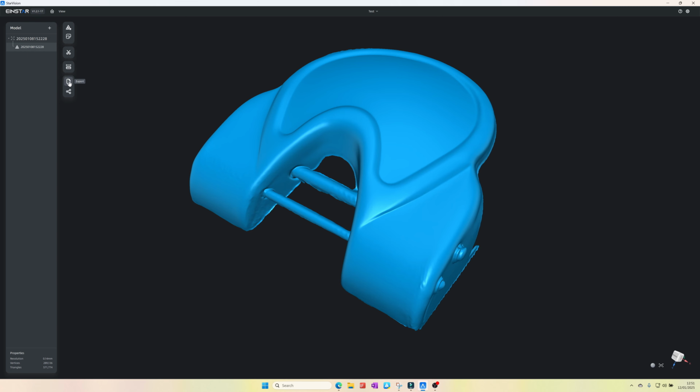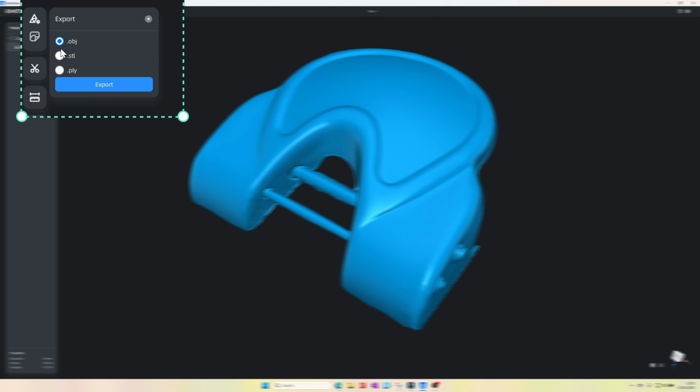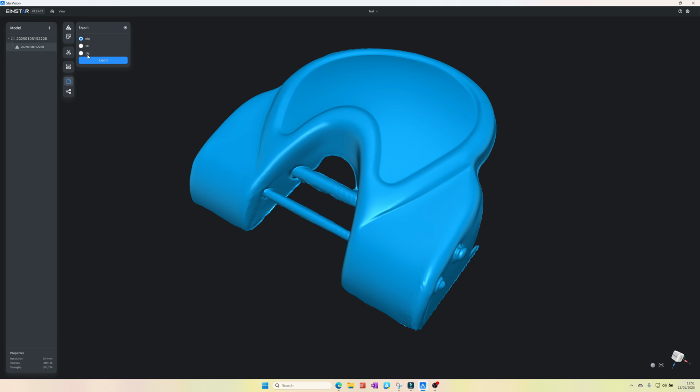If you're planning to continue working on this in Autodesk Fusion, export it to the computer. You can use OBJ or STL formats. Ply doesn't seem to be something Fusion can natively open, as it's a point cloud, but I'm pretty sure I've seen a plugin somewhere that allows this operation. However, the OBJ format as well as STL are guaranteed to open in Fusion.